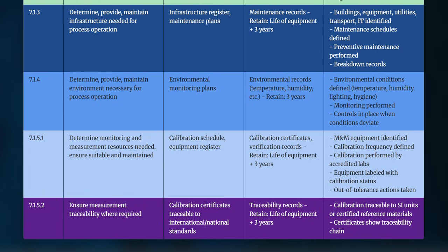The evidence you need to present to the auditor here includes calibration that must be traceable to SI units or certified reference standards, and certificates that show the traceability chain.